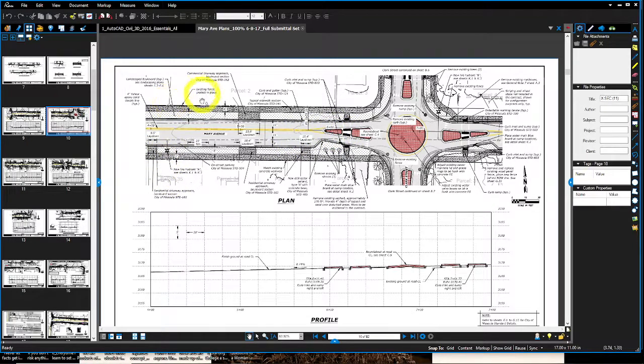So there's a slice here at 500, there's a slice at 550 here through the road, and there's a slice at 600 going into this roundabout. So those views were depicting the perpendicular slicing to this alignment here. So there's a real world road plan of a city road.